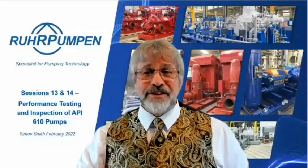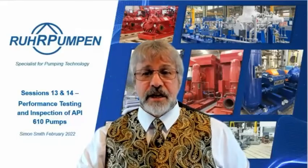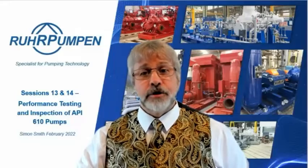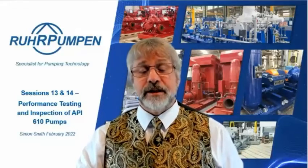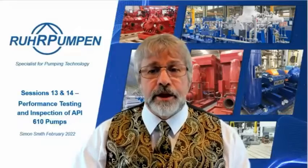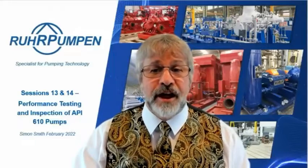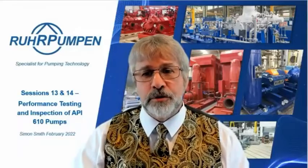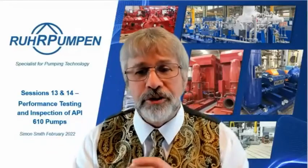I would want to do retests on those, because it suggests that the two impellers have not been machined in the same way. So you do need to strip it down and have a look and analyze what has gone wrong. And as for making a pump that has a hump not have a hump, there's no magic wand that can be applied to that. It's the design of the pump.